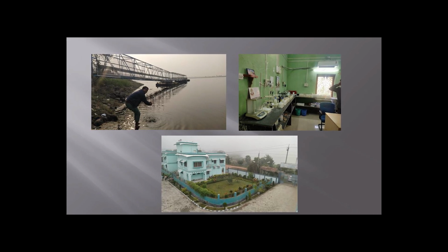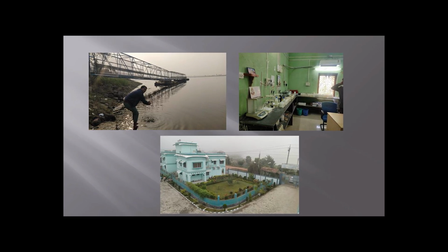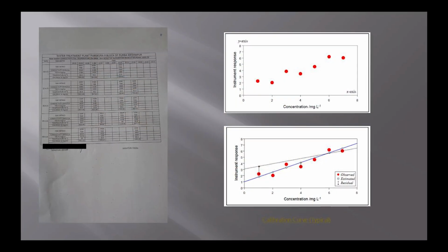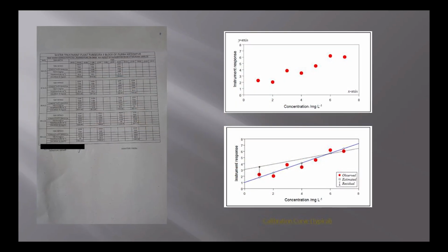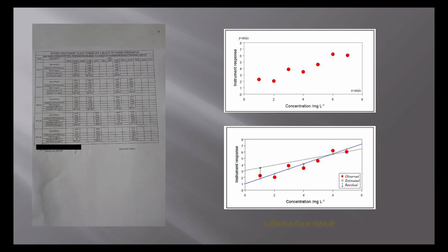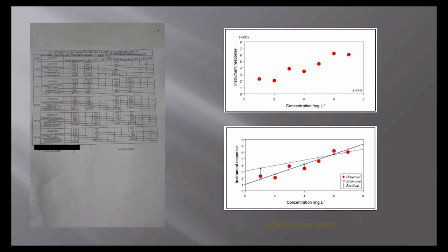It needs validation from primary data. That exercise was done in a government accredited laboratory by examining the samples taken from the river at those monitoring locations at different times of a day and correlating with the instrument data. Here, the real challenge is to establish the correlation factor. Procuring different companies' instruments for a single stretch of river in a single project is not applicable or recommendable.